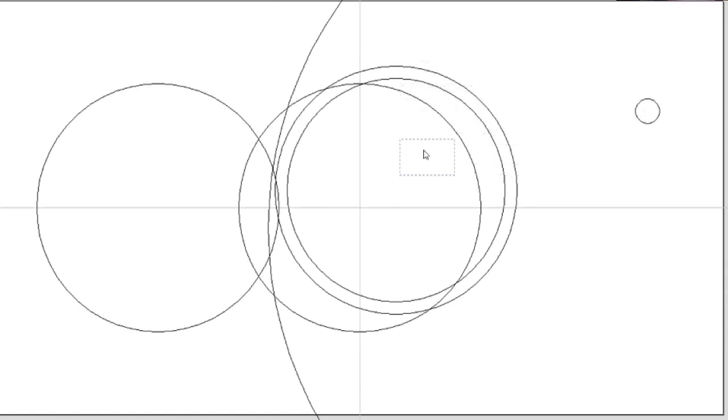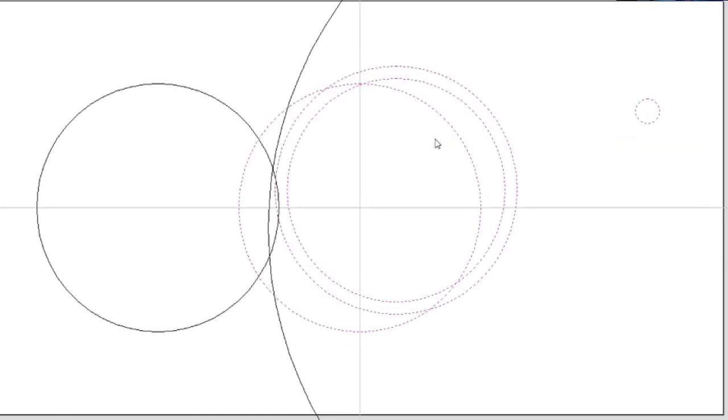Oh yeah, see the circle is hidden behind our pictures. Drag our picture down to the lower left. Okay, I'll do it again. Left to right now. So you were right on a vector when you did that. It didn't pick because the circle was not completely inside the box. From left to right, any object that's completely inside the box that you create will be selected. But if any part of that object is hanging out, it won't select it.